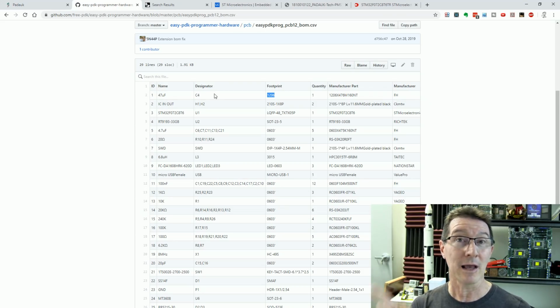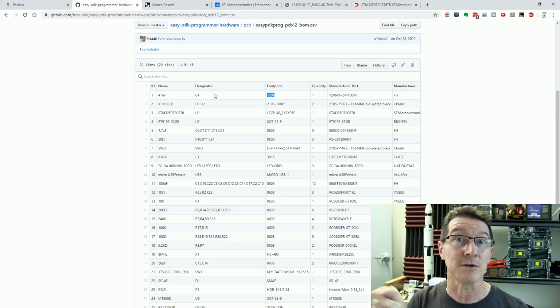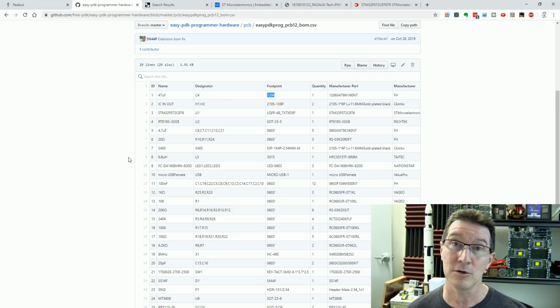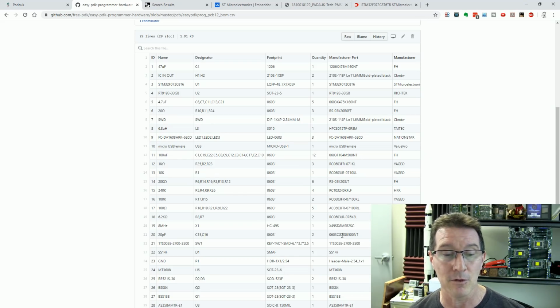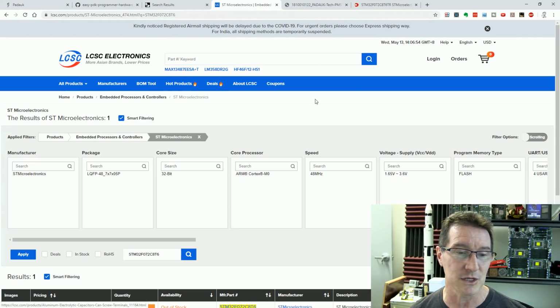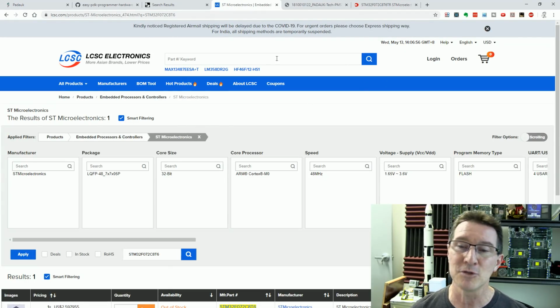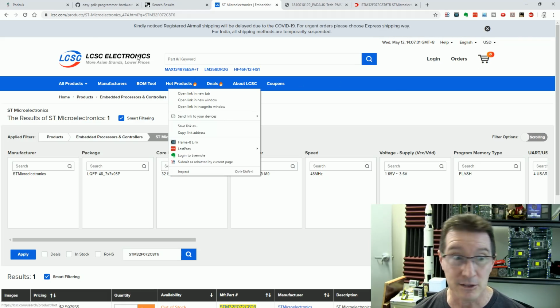And they should put a little asterisk on the schematic and annotate that saying it must be this part because reason. So that's a little tip if you're designing products: annotate your schematics with useful information like that. Anyway, the point is you can go down and copy all these one by one into your DigiKeys or your Mouses or your LCSCs or whatever, and then you add them to your shopping cart. You choose how many you want, you add them to your shopping cart, and it's tiresome.